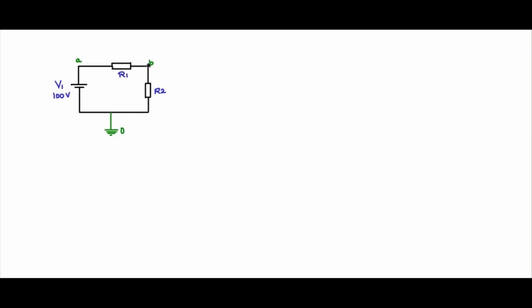This simple attenuator circuit, we have seen how we go about simulating in ngSpice. In this session, we will introduce one more component. We will see how we invoke models, subcircuits, and refactor the .cir file into subcircuits netlist and .cir file.